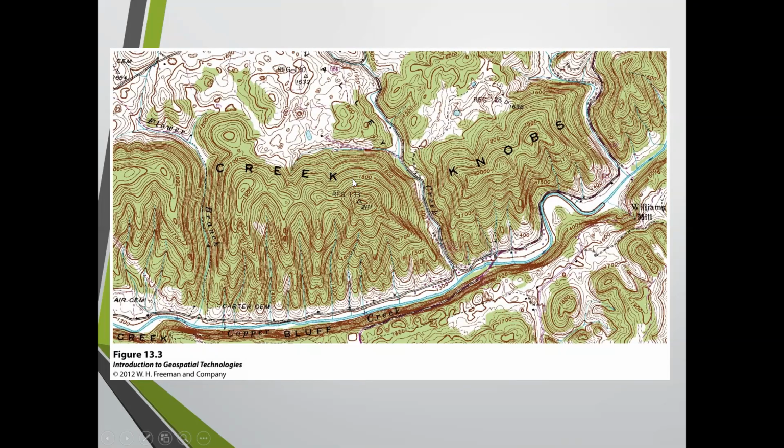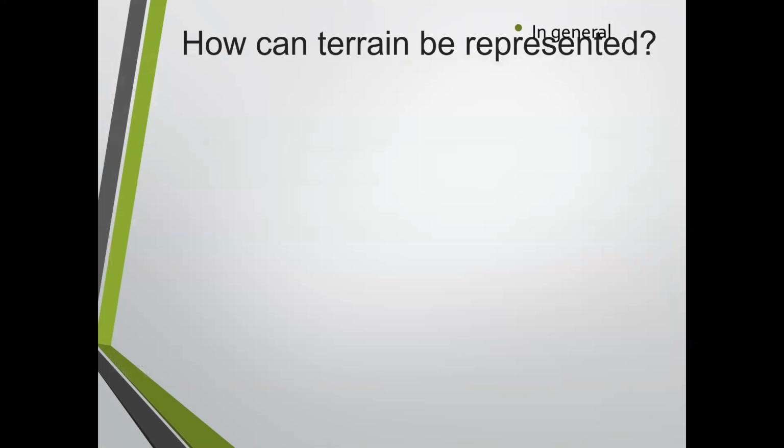So if you took 100 feet divided by 5 spaces, that would tell you each contour line at that point then represents 20 feet of change. So that's kind of how we do that. Of course, the beauty, this isn't fixed paper, so you can't change your interval. But if you guys know things about Civil 3D, I can express my contours at any interval I want very readily. So I can make a 2-foot interval or a 1-foot interval or even a 1/2-foot interval just by basically flipping a switch. So that just has revolutionized how things work.